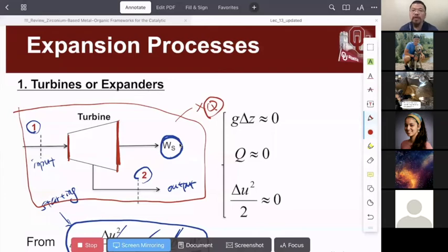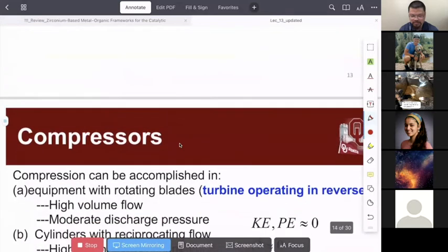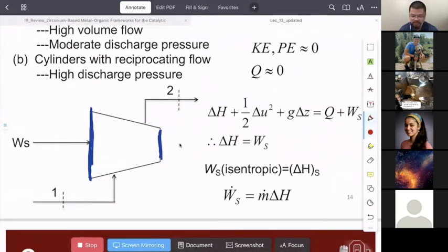So I hope you quickly realize that the compressor is the reverse unit of the turbine calculation. Okay? This is the first thing I want to mention. The second is that we are still starting from the first law for flow process, and we come to the equation of this for the reversible isentropic process, right?